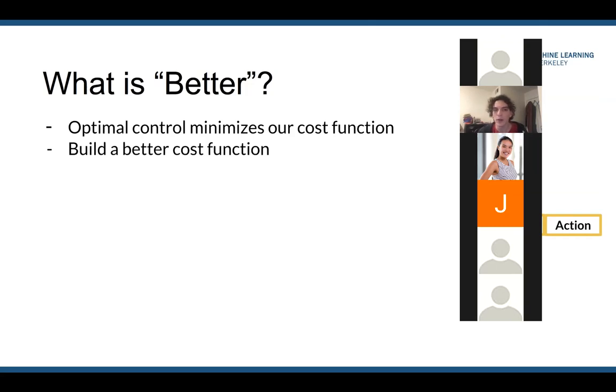that actually represents what we mean when we say better. So in PID, we were trying to get error to 0, which we do want, but we also have other considerations. One consideration is we don't just want to get to the goal, we want to stay at the goal, and we care if we overshoot, which we didn't encode in PID. We just said get the current error to 0, and it did that, but then that made future errors really high. So we somehow want to incorporate the future errors into our costs, not just the present one.